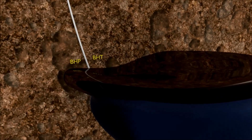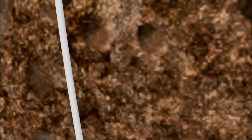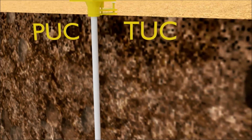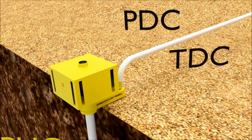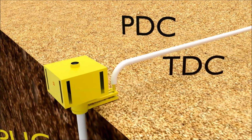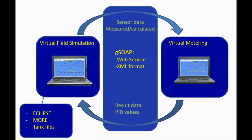Based on measured sensor data, allocation of well phase flow rates can be performed using virtual metering calculations. Any flow-related data can be used, but pressure and temperature sensors located downhole and up and downstream of the choke valve are most common. As an alternative, allocation curves can be used, providing phase flows directly from a measured well pressure, assuming a fixed gas-to-oil ratio and water cut.